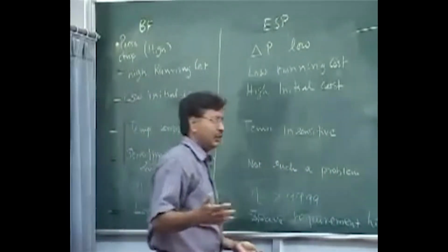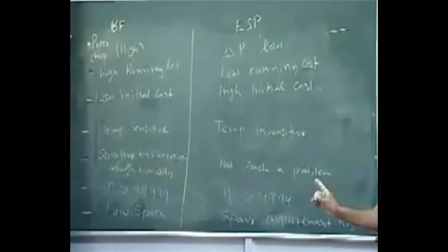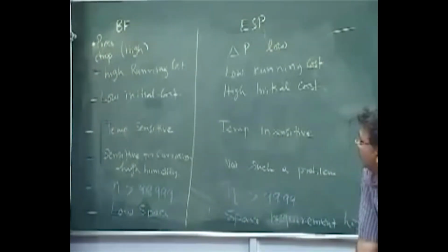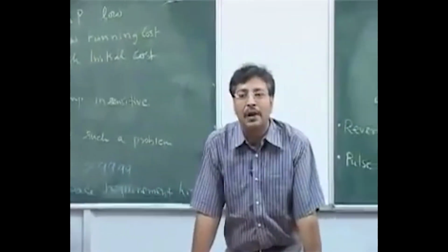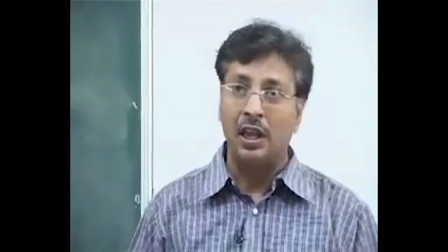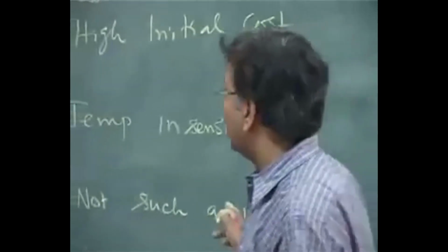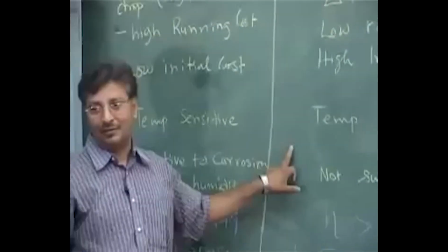These are the differences. I think we'll have to stop there. If some point is missing, I will cover that. You can see the choice between bag filters and ESP can be a little tricky, and people, depending on what process they are dealing with and what they want to remove, choose accordingly. The other thing is that the ESP, as we have talked about, can be a little bit prone to fire.